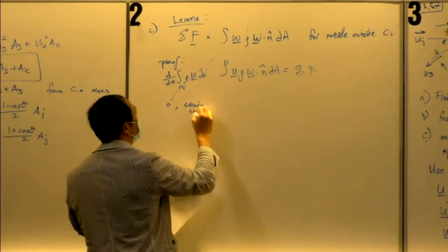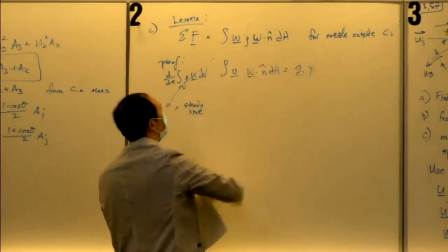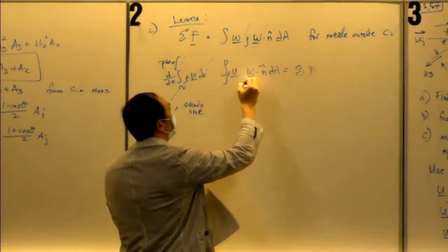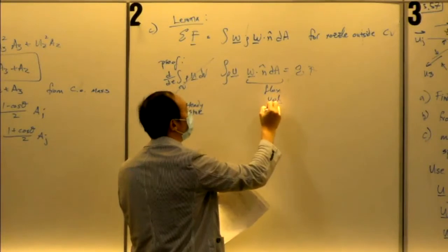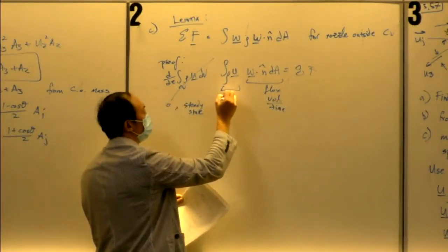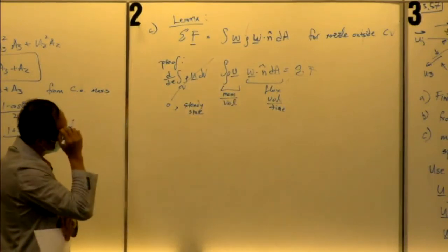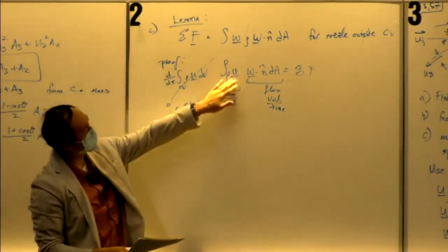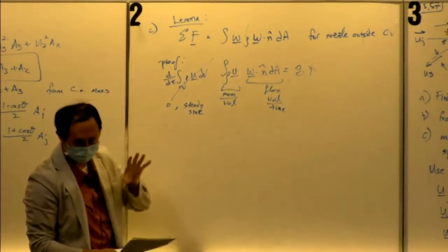Let's just keep the rho in front. This is the flux, which is volume per time, and this is the linear momentum, so momentum per volume. This is defined in the lab frame, and this changes if your control volume has a different speed.